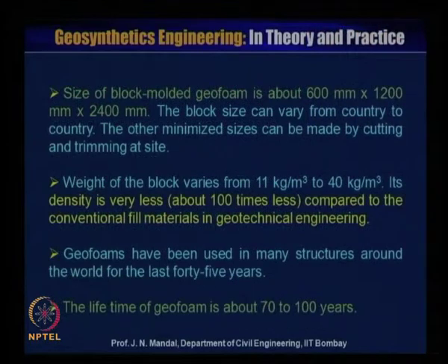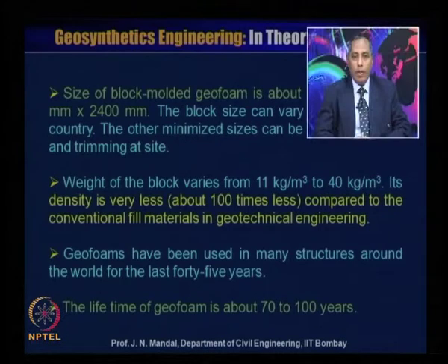The size of the block molded geofoam is about 600 millimeter into 1200 millimeter into 2400 millimeter. The block size can vary from country to country. Other smaller sizes can be made by cutting and trimming at site.